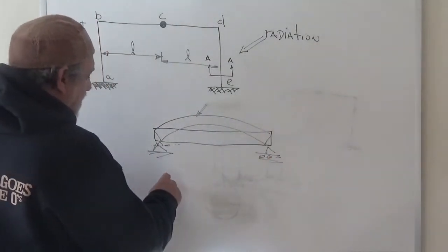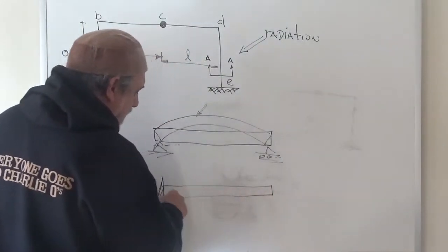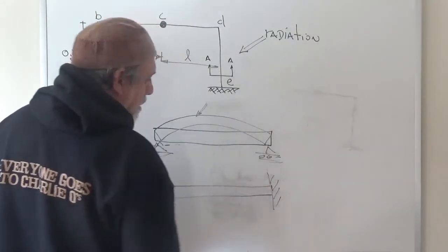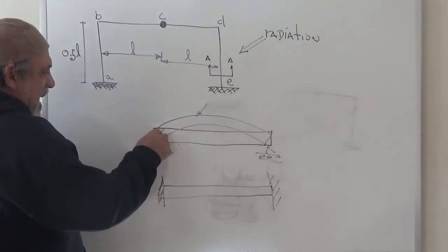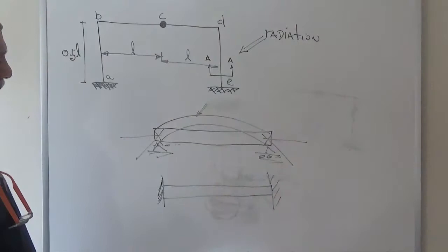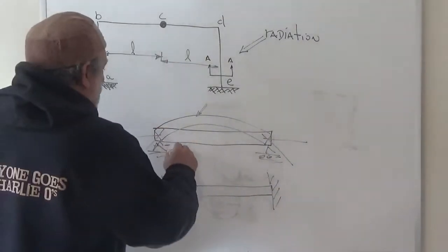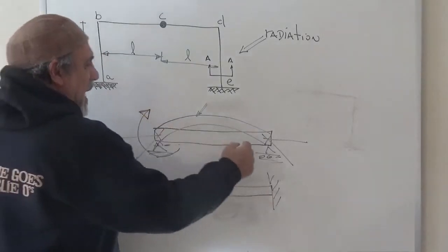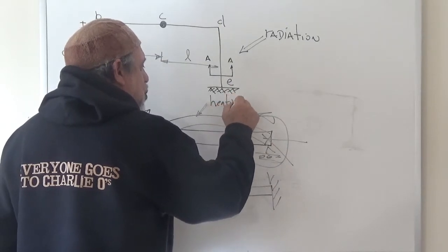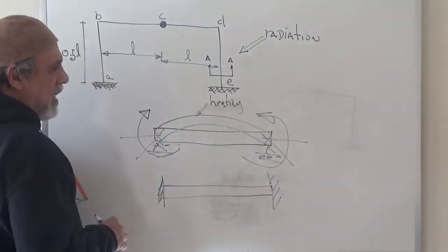Now, if the beam had been not simply supported, but double fixed, then it's obvious that these angles that the simply supported beam takes when I heat it up cannot occur over here. Therefore, some moments would appear at the ends of this beam due to this heating to ensure that this condition is satisfied in the doubly fixed beam.